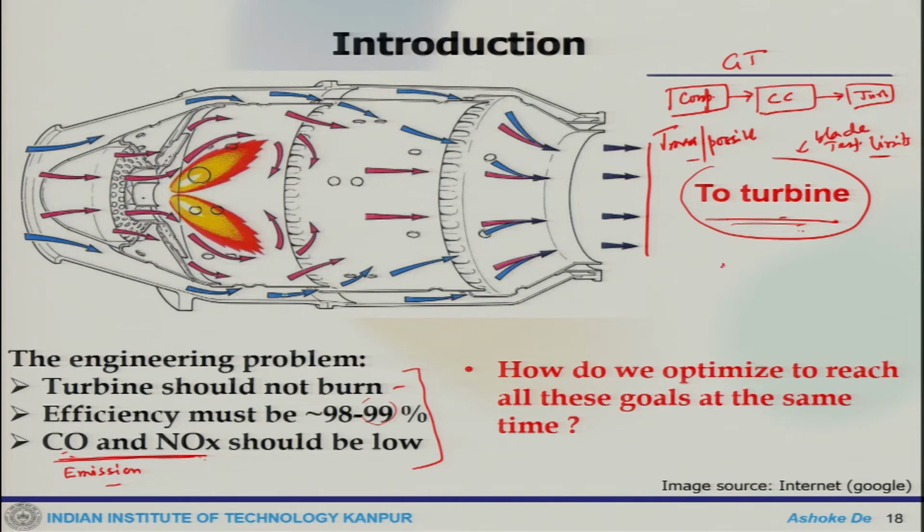If one plots the temperature axis against NOx and CO, at too high a temperature this will go up and this will come down. But if you go to too low a temperature, CO will go up and NOx will be low. So, even in the emission products there are different characteristics. It is a trade-off; one needs to operate a system within a bandwidth limit of temperature.